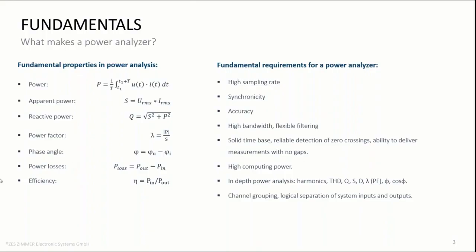To conclude and summarize, a power analyzer is an instrument with integrated current and voltage inputs, high sampling rate, careful channel design, and high computing power that enable it to measure and analyze broadband power with very high accuracy on electrical circuits and systems.